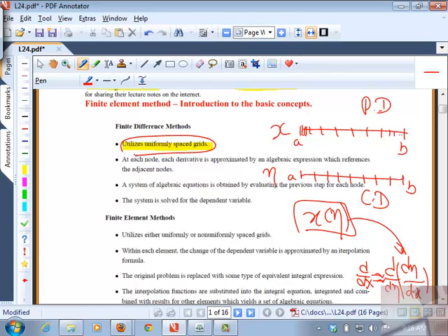But the more challenging problem is if I have a domain that is not a rectangle or a cylinder, then even if I do this transformation, it would be a bit challenging to make my uniformly spread grid points on the transformed domain fit in that. People have also come up with solutions for that. Okay, and that is what is called boundary fitted coordinates. So if you have an arbitrary geometry, then you will build a coordinate system that kind of fits with the boundary.